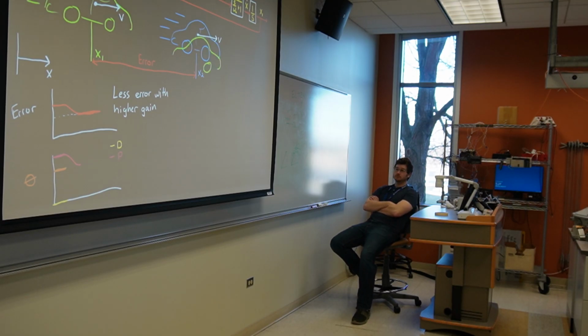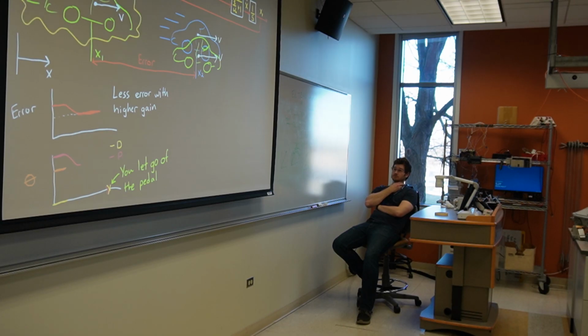You can easily see the flaw in this thinking by assuming you started out at the exact speed and location as your friend, and you use a PD controller. In this case, both the proportional and derivative error terms are 0, so you immediately release the pedal and start slowing down. So by controlling pedal position and using a proportional derivative controller, we have no way of bringing the steady state error to 0.